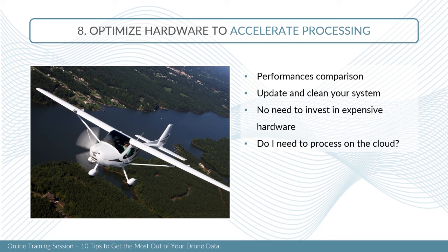So it's really a matter of what your organization needs. If you have a very big organization and you need to access the processing from different offices, different locations, the option of using the cloud can be interesting. But if you're always doing small survey projects, I think you can even have a laptop, bring it to the field, download your images, and process them ad hoc while you're in the field, and that's going to be a lot faster and more efficient than setting up a cloud, uploading the images, processing your project, and downloading the result.